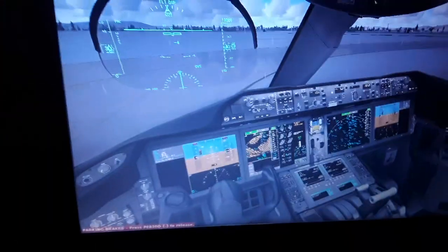So we have Zurich International Airport, LSZH, and runway 14 LSZH localizer frequency for this purpose. We also have the LSZH localizer crossbar. We have the flight director crossbars for manual guidance of the aircraft and the autopilot crossbars for automatic guidance of the aircraft. We also have the angle of attack of the aircraft, and the flight modes: the autopilot and the autothrottle, and later on the vertical navigation modes.